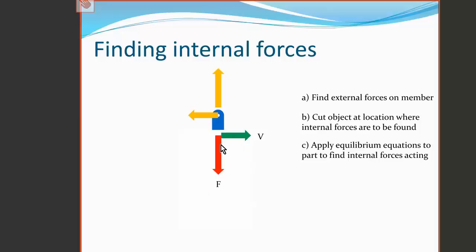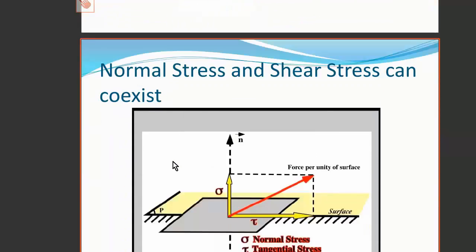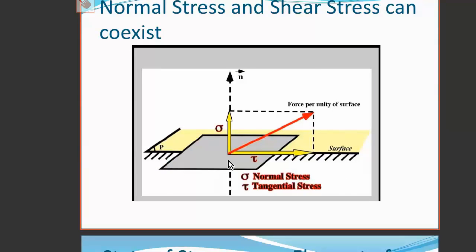If we divide these forces by the cross-sectional area, we convert them into stress. That's shown in this diagram here. Imagine we have a force acting in a particular direction on an area. If we divide the component of that force that is parallel to the area by that area, we get the shear stress, called here the tangential stress.